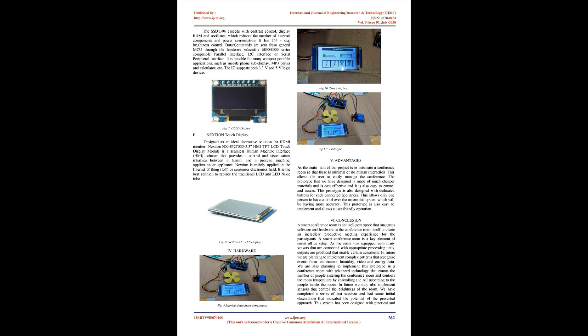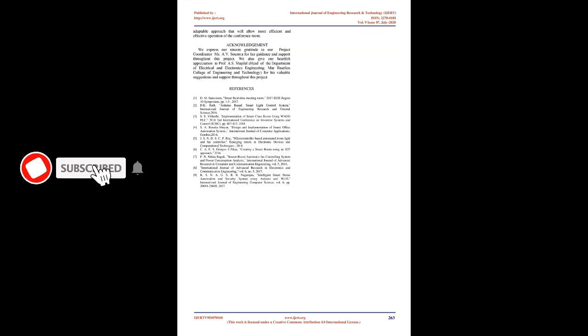OLED display SSD1306. SSD1306 is a single-chip CMOS OLED/PLED driver with controller for organic/polymer light emitting diode. Matrix graphic display system. It consists of 128 segments and 64 commons. This IC is designed for common cathode type OLED panel. The IC supports both 3.3V and 5V logic devices.